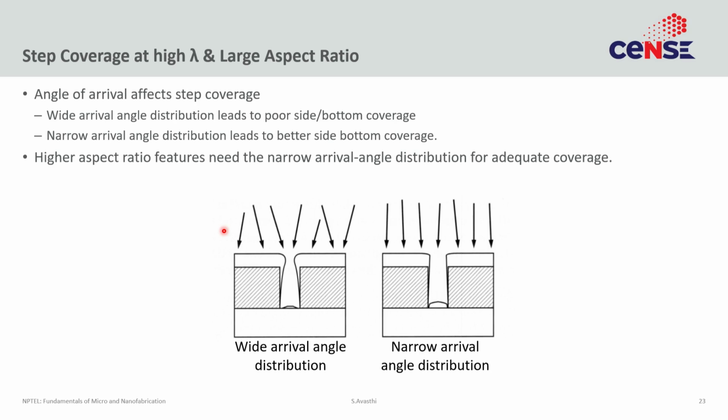Let's talk a little bit about step coverage. So we discussed that CVD is often very good at step coverage because it's temperature radiated, etc. But here there is no effect of temperature so much. Often the substrate is at room temperature. What you have to be careful about is the direction of the incoming flux.